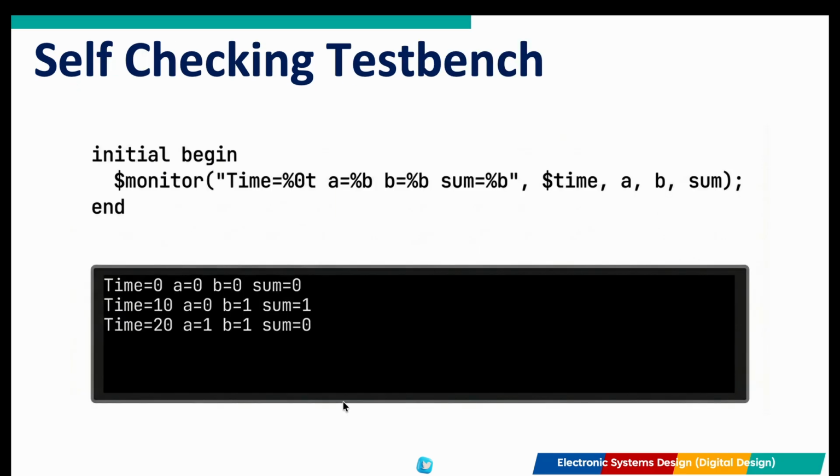While looking at waveforms is great, manual inspection is tedious. To automate the process, we use monitors and assertions. Verilog system tasks like $display print one-time debugging messages, while $monitor continuously tracks specified variables, printing a new message whenever a value changes. For formal checking, we use assertions.